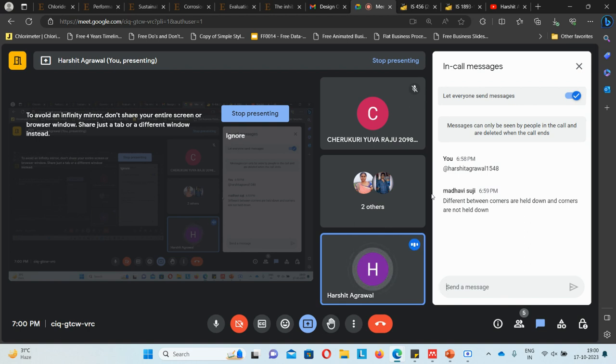So generally, when we talk about certain elements where there can be both negative and positive moments, we talked about how the corners can experience some torsional activity and they can be held down. That's why we design for torsion also in those cases. And when no negative moment can generate at the corners, we generally say it is not held down. For more on this, you can refer to the week 6 content again, and you will have better clarity there also.